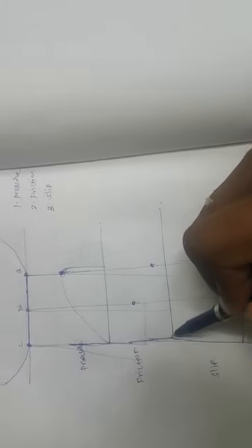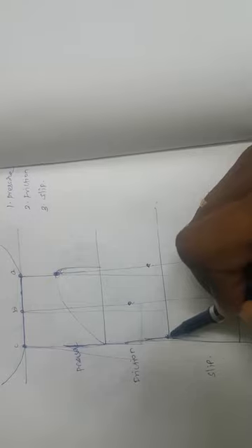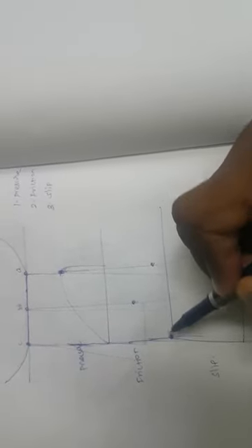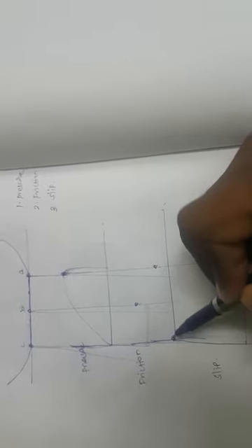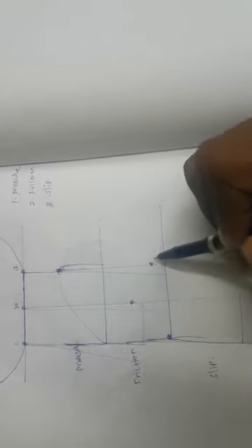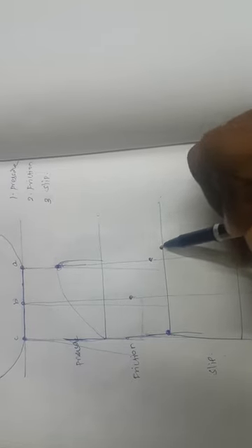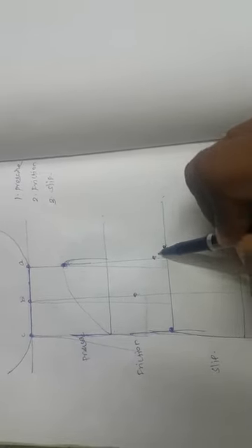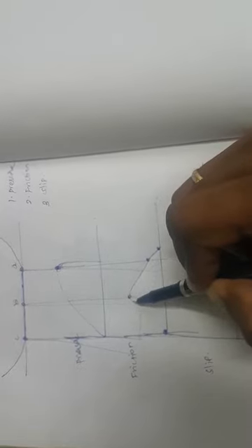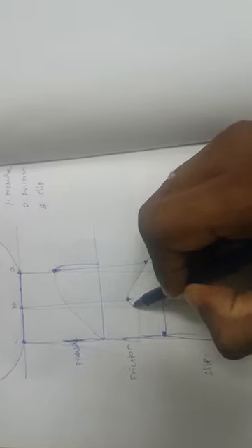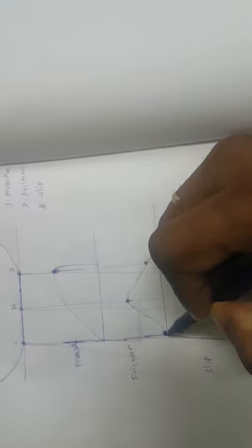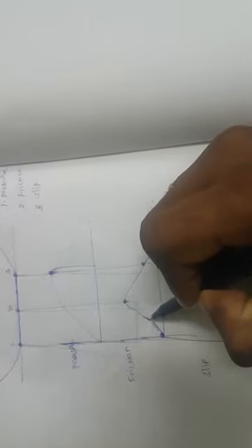So at point C you feel zero friction, right? From free rolling it comes like this. Immediately after releasing from the contact patch, you feel an immediate release of friction. So it will not be a straight line, it will be a curve, right?